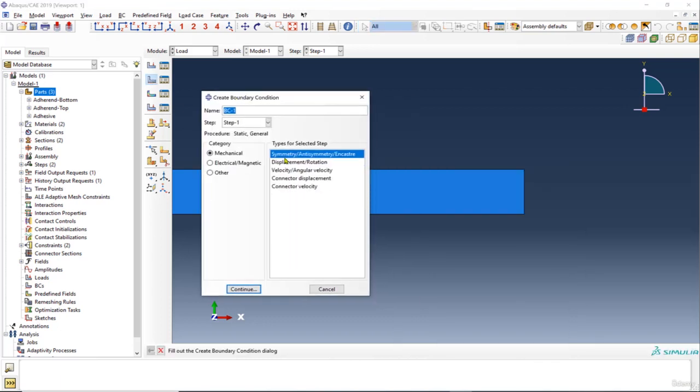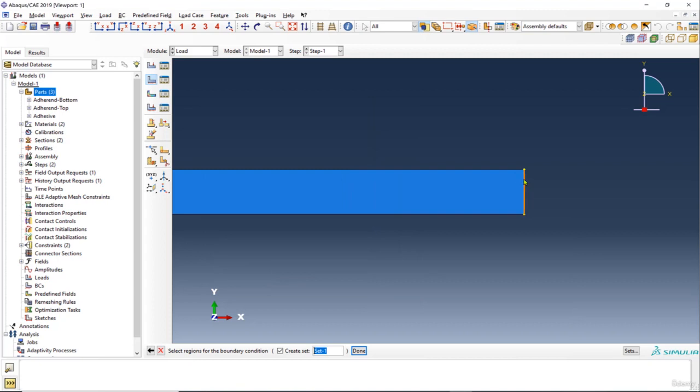So if I go here, displacement, I can apply displacement to a line. But the problem is that when you apply displacement to a line, and especially if you have a large displacement, it will cause a mesh distortion around this area, and that might cause an issue. So I recommend you to again do the same thing and create a point here or node, and couple that point to this line, so you won't have the mesh distortion problem in that area.